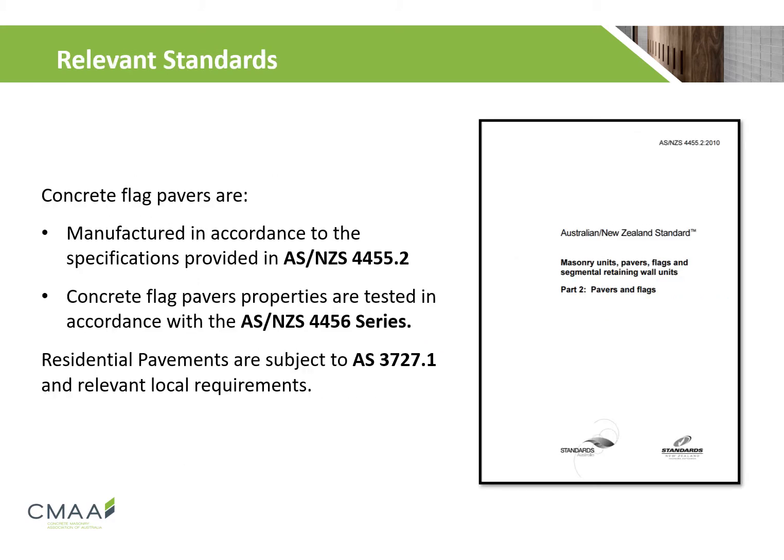Concrete flag pavers are to be manufactured in accordance with the Australian New Zealand Standard 4455.2. This standard outlines minimum paver material properties with respect to the surface's functional use. The Australian New Zealand Standard Series 4456 dictates the testing procedures used to identify the aforementioned material properties.